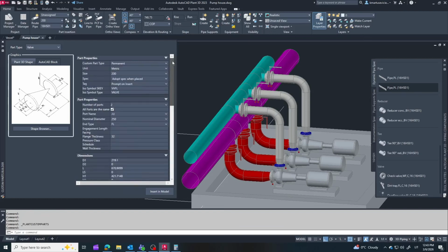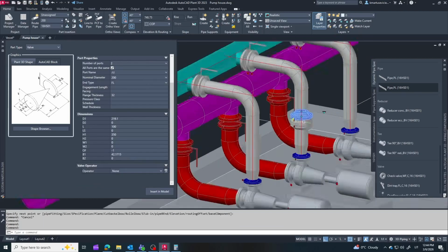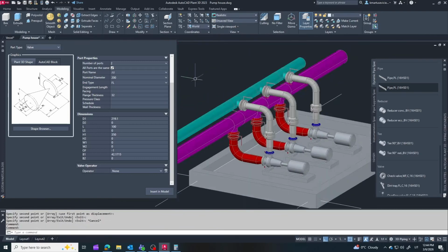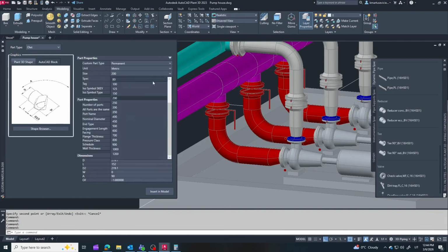The purpose of a check valve is to allow the fluid to flow in only one direction and prevent backflow. This is especially important in pump systems because when a pump stops, the fluid could otherwise flow back and potentially damage the pump or rotate it in the opposite direction.